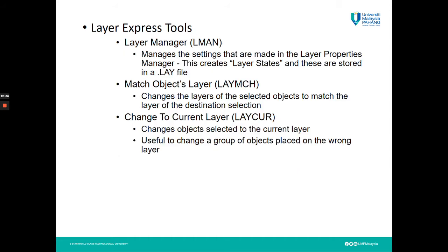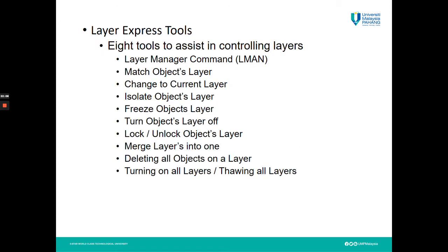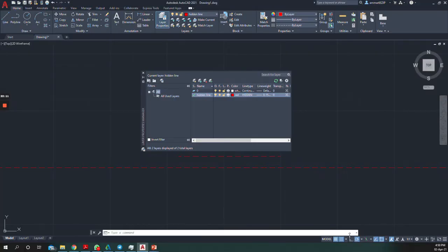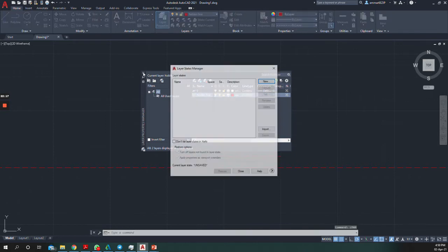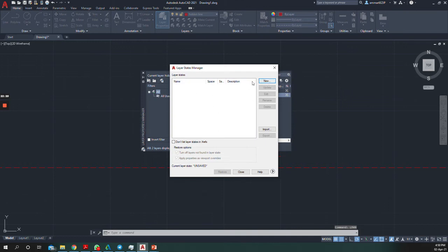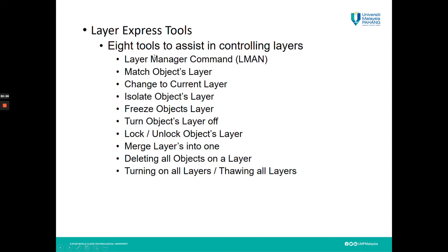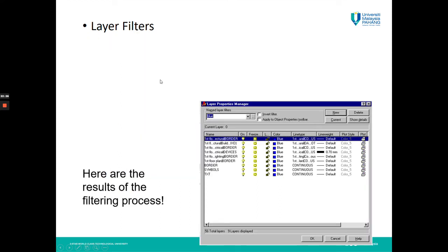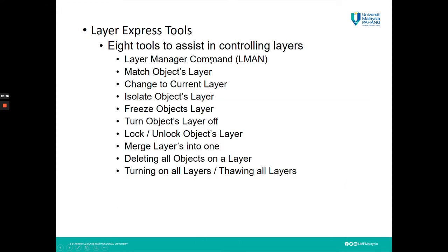You can also use many other commands, like LAYERSTATE. Layer state manager will help you to manage the different objects' layers, change the current layers, and apply all of this information up here to your layers.